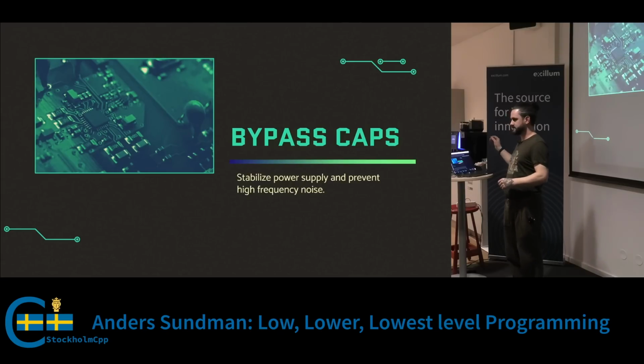And there are two main use cases. One is to supply an extra boost of power if there's a voltage drop because you turn on something somewhere else. And the other one is to reduce the RF emissions that come from the CPU, which is very noisy. It turns on and off and on and off. And the power circuitry can turn into RF antennas transmitting at high frequency if you don't do something about this noise.